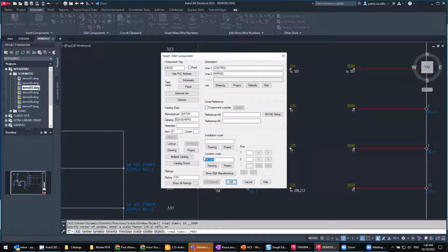And this is something that I strongly encourage the designers to use, because once you start working with large projects, trying to generate reports and trying to narrow down your list of information to make it a lot smaller is going to be hard without a location. For example, you want to create a BOM only for a location that maybe it's floor 1 or panel 2. Instead of creating a BOM for the whole project, I can narrow this by specifying the components. This one's located in panel 1, this is located in panel 2. It's going to be a lot easier for me to manage that information.